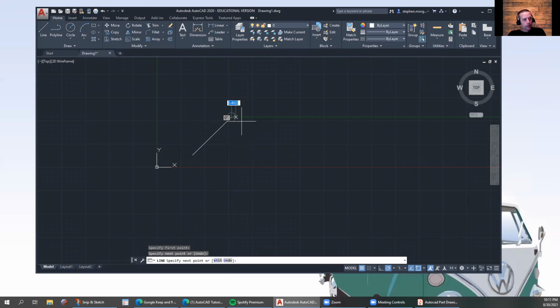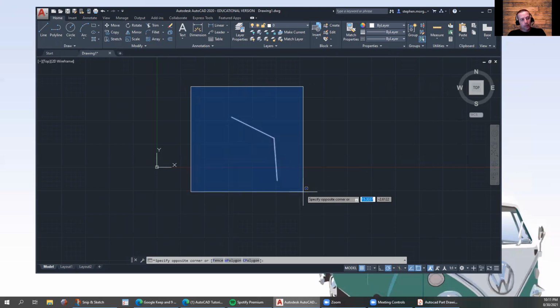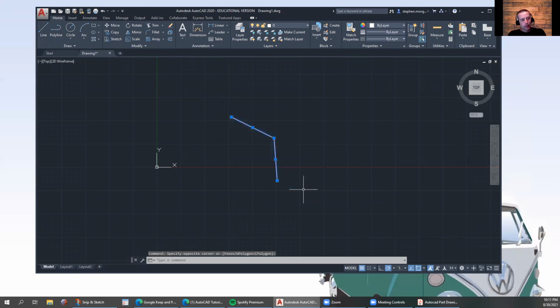So if we did this, we can start drawing some lines. If we want to delete a line, we just click it and press the delete key on your keyboard. And then if you had a group of lines that you wanted to delete, or a bunch of geometry, you would go to the upper left corner of the group, and you'd press and click and let go. Press once your left mouse button and let go, and then you get a nice selection box. You can do that.